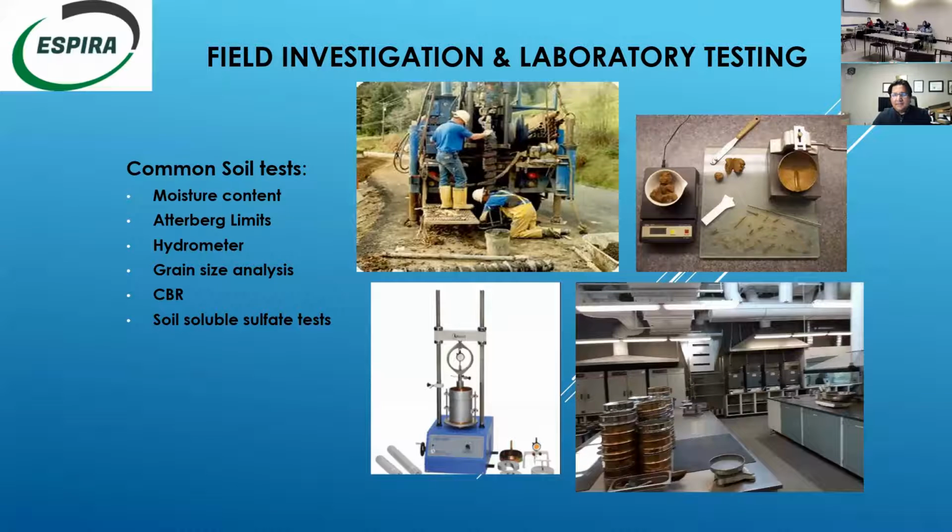Hydrometer, typically, again, the engineer of record performs this test to find out the particle size distribution of fine-grained soil. Grain size analysis, same thing. They want to know what the particle size distribution of a given soil sample is to make some recommendations. Also, the other test done is the California Bearing Ratio Test, or CBR. It's a penetration test used to evaluate the subgrade strength of roads and pavements.